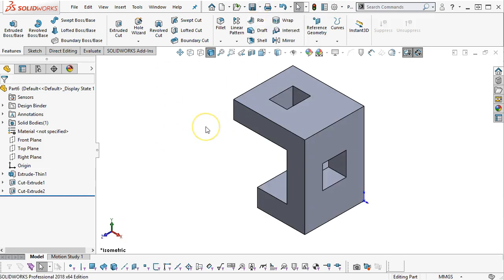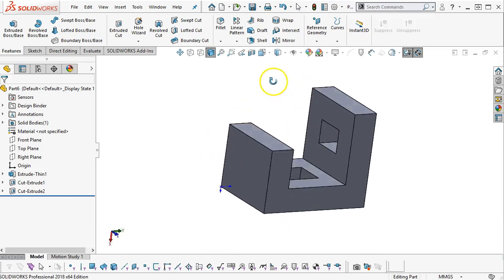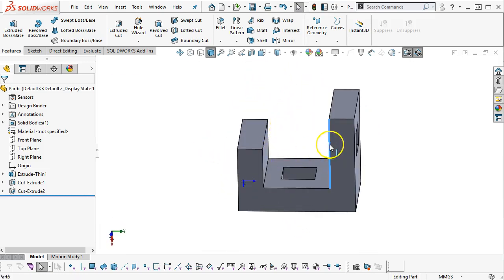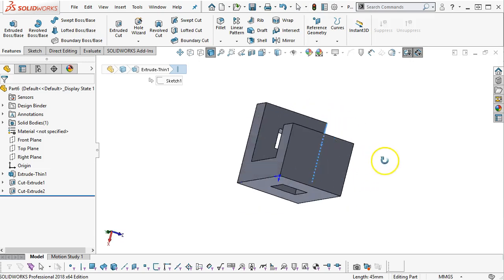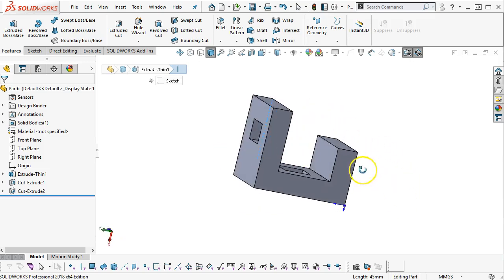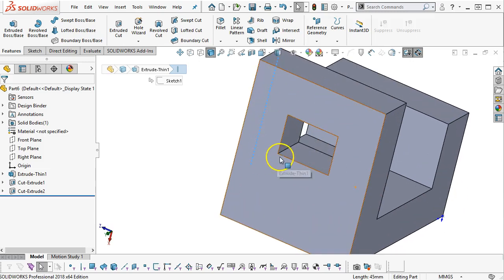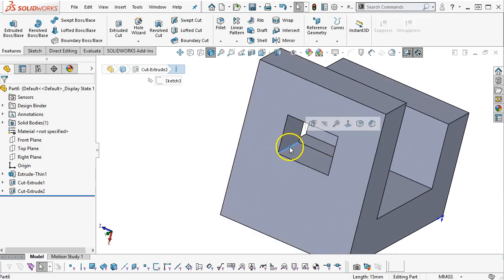All right. So one of the considerations in the manufacture of this part is we're 45 millimeters, so not quite 2 inches. That's a little deep. We could get these square corners in and remove that geometry. What is going to be an issue, especially on this face, is these square corners.